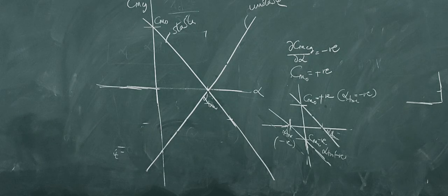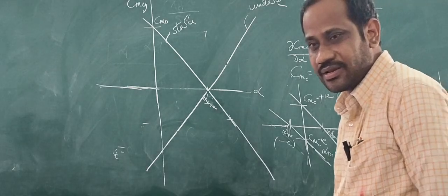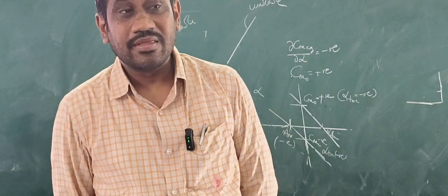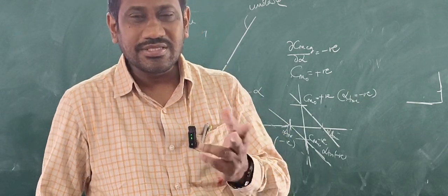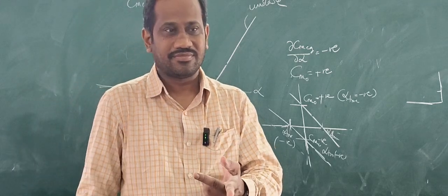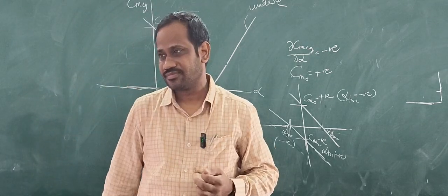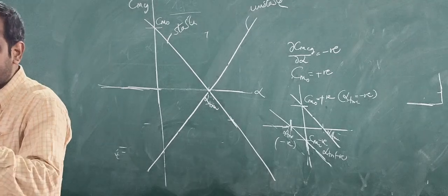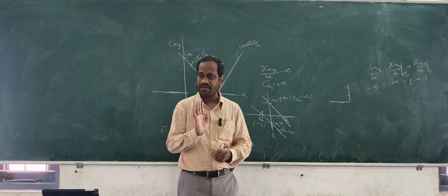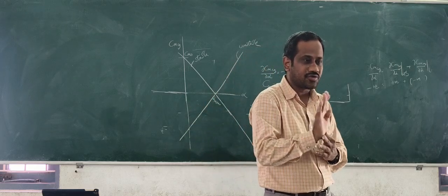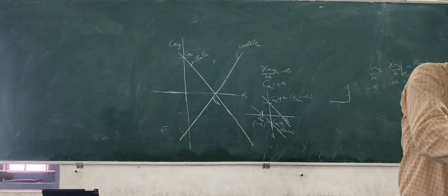Please note this down and have a discussion. The aeroplane can still be stable if Cm naught becomes negative, but the equilibrium angle of attack, or trim angle of attack, is negative. Negative is not desirable. That's okay, negative is not desirable. Positive is desirable. Why is negative not desirable? The aeroplane always tries to point this way.